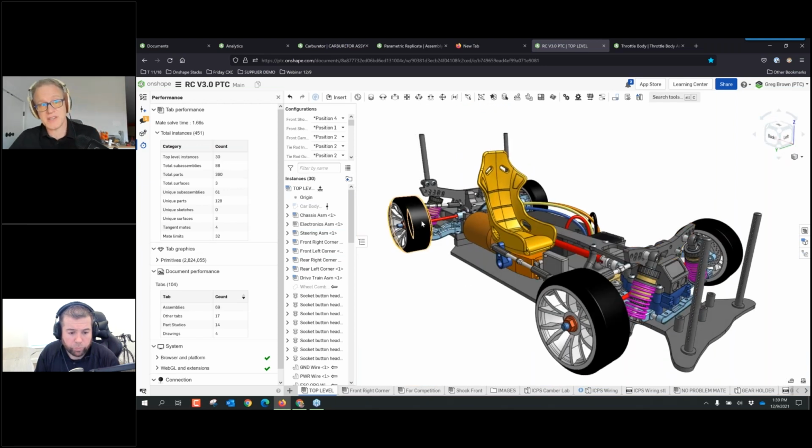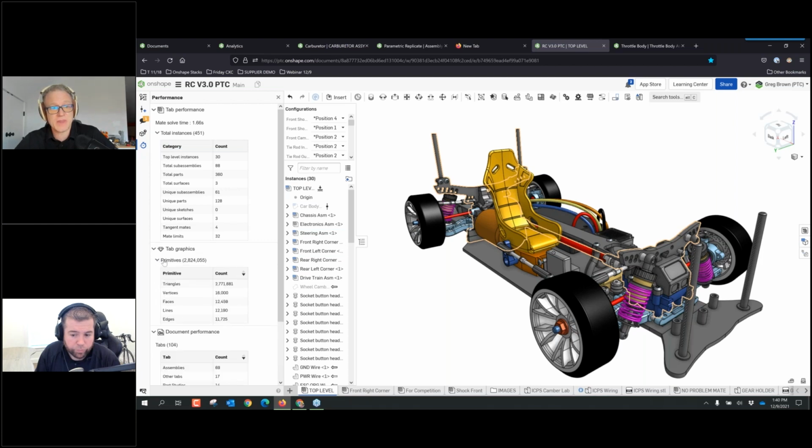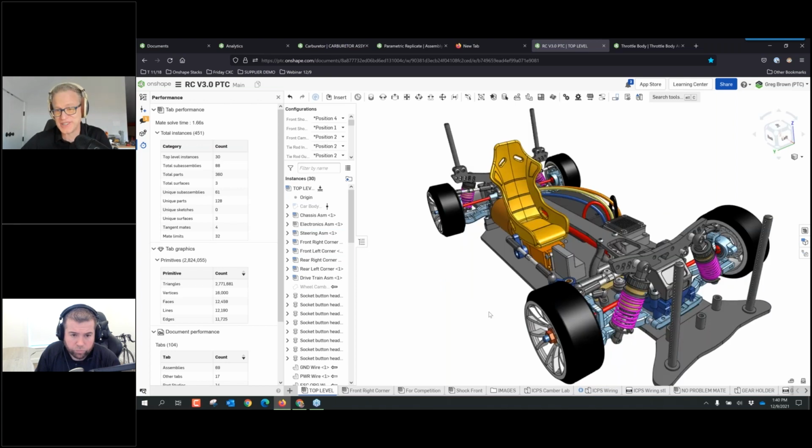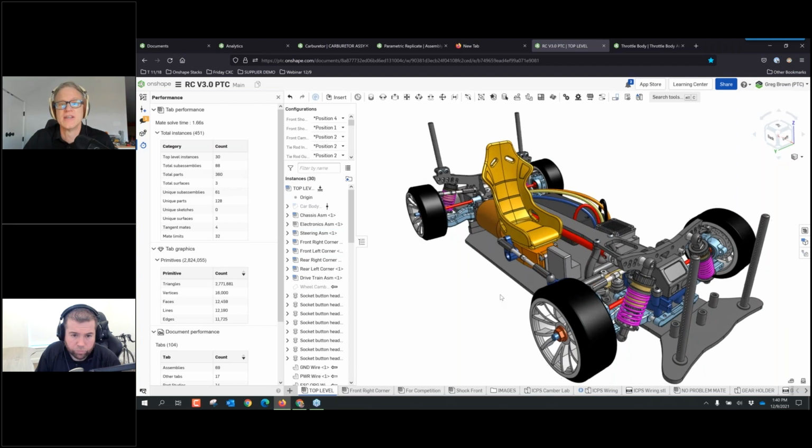The other really interesting thing in this view here is with graphics. And I saw this on the forum the other day. Someone was asking about how do we know if there's a very fine tessellation. In fact, you go to the same place. You go to this performance monitor and pull down here. And if there were any very fine tessellated parts, it would say that you've got one very fine tessellated part, or 2 or 10 or whatever. So yeah, there are ways to do that. And for whoever, if the forum poster is on this call, then welcome and thank you for joining. But also there's your answer.